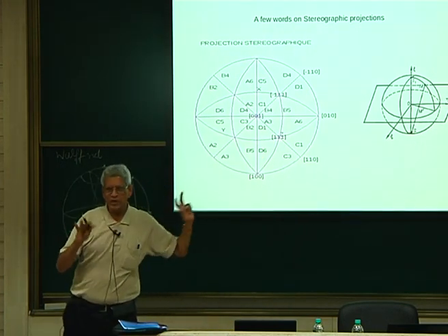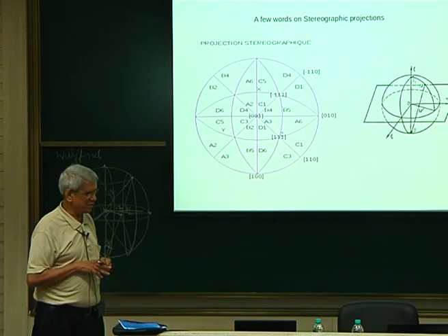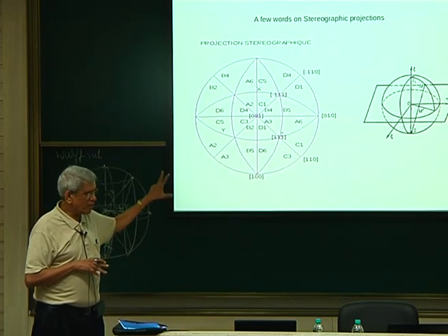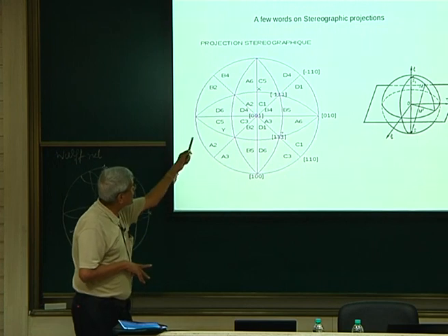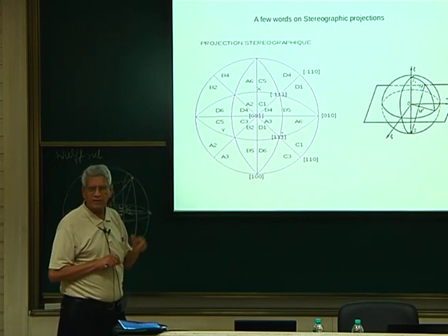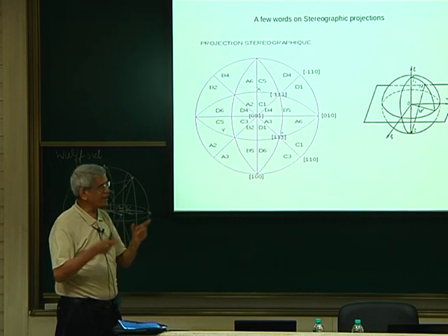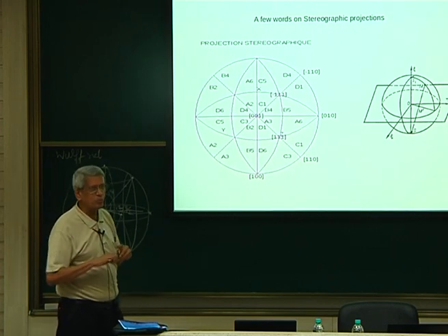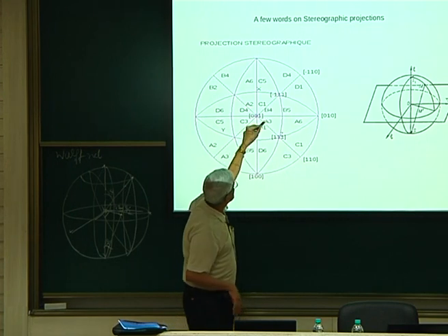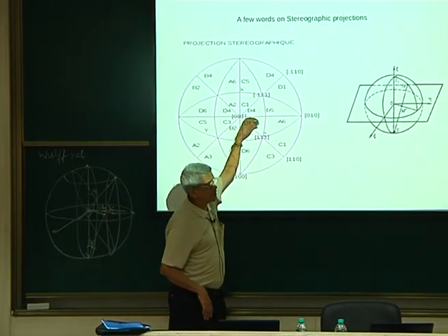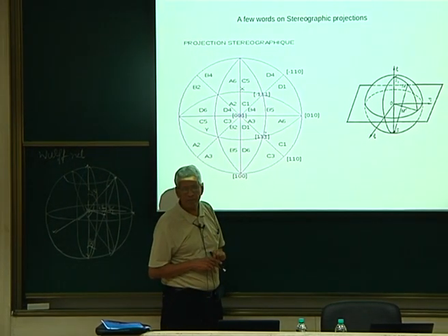These things one can calculate and just show it here. So this is how we can find out all the slip systems that are going to be there. Then another important factor, I think, as Marc has explained, suppose this is the initial orientation if we start with.